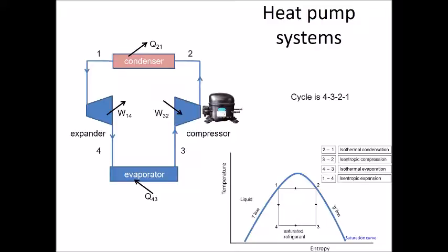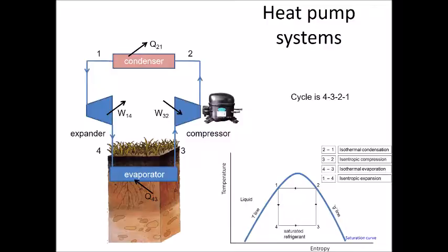Well, my compressor does the same thing. My compressor is just a pump, and it's moving refrigerant around the process. Okay, we're happy with that one. Now, my evaporator, if you remember from last time with the refrigeration process, was where the food is stored, and it pumps heat out of the thing to be refrigerated. In a heat pump, that's not what I'm interested in. I don't build a heat pump because I'm trying to cool down the land or cool down some water or something like that. That's not the idea. The evaporator is the source of heat, which I'm going to move. It's a low temperature reservoir, and I'm going to pump heat out of it.